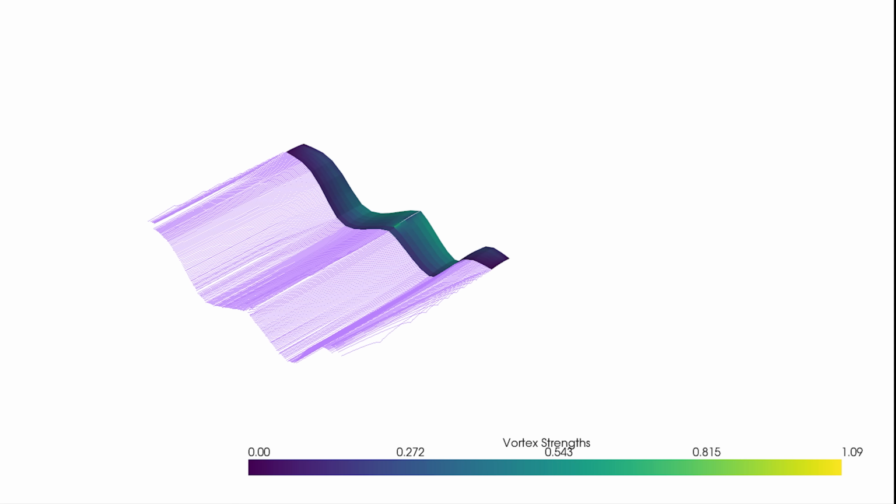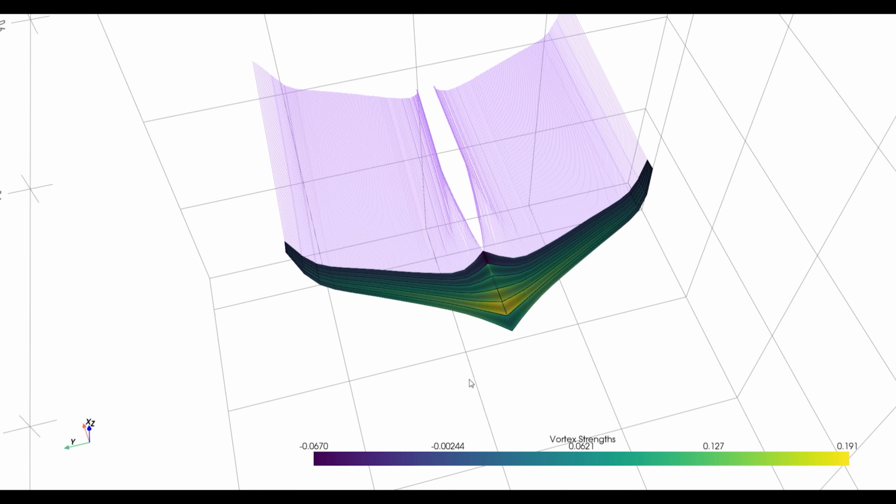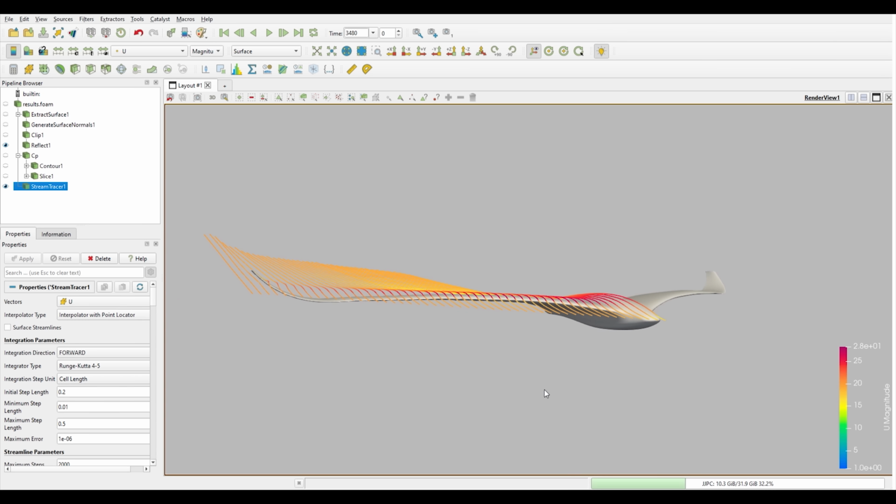And since it is a simplified method, I validated it by comparing VLM results against CFD on the reference wing, making sure the trends match well enough to trust it for the search.